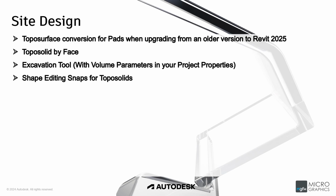Next up, for site design, I will take a look at topo surfaces and topo solids. Previously, topo solids were called topo surfaces. When you upgrade your model from an older version and open it in 2025, it will automatically excavate that surface with the topo solid.